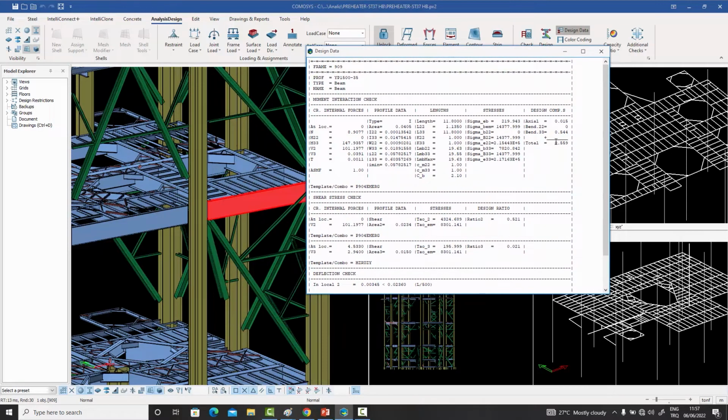And this time the design data is filled. And you can see over here your final stress results. This number should be less than 1. Basically, the summation of your axial forces plus your bending moment in 3-3, the total should be less than 1. Right now, it is less than 1. And it'll give you the exact locations. It'll say that the most critical combo was this one. At a location of 0, the axial force was this much, the bending moment was this much, etc. Your lambda or inertia parameters are given over there, your K factors, your L unbraced lengths, and your design related variables, and the final analysis.